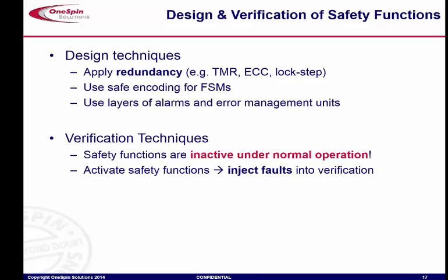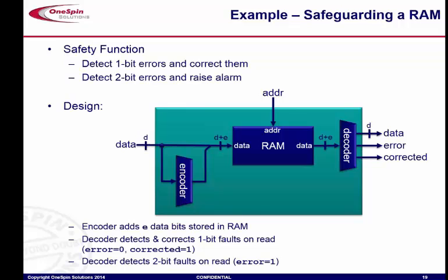And of course, the problem here is that all this stuff you put in does not happen in normal operation mode. So your normal simulator and your synthesis tool would think this is kind of redundant stuff. It never triggers or it doesn't affect I/O behavior. So actually to verify it properly, you need to inject faults in your design and perform additional verification with injected faults. And we pick here a very simple example, just also looking at ECC.